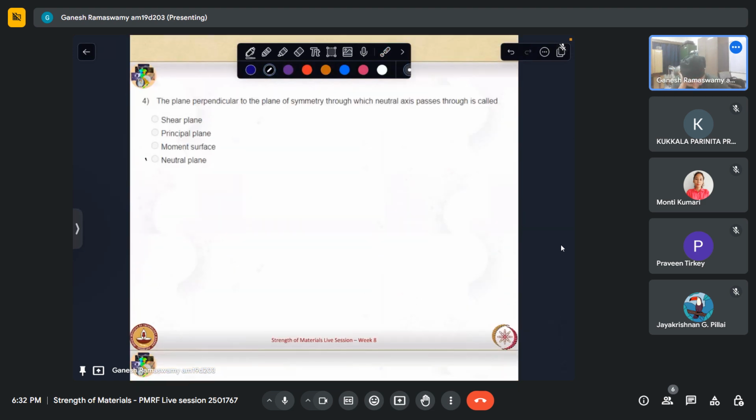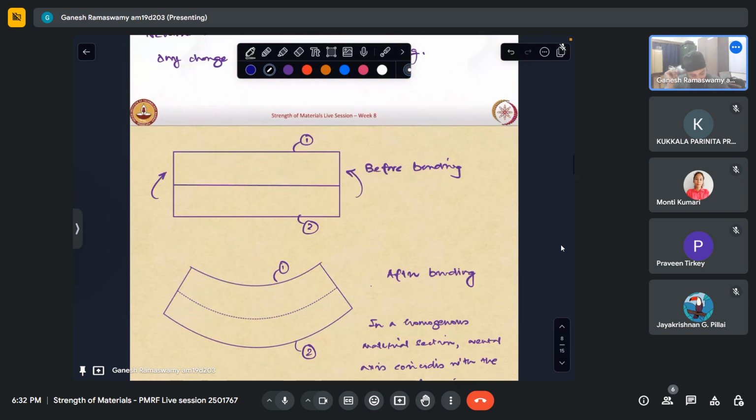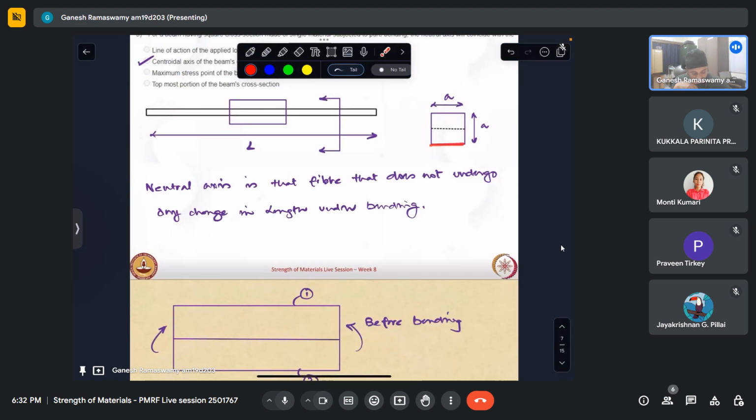But why is this important? It is because we are looking at one surface of that beam. We are not looking at all the surfaces of the beam, because naturally when we see here that there is tension and there is compression, so if there is tension at the bottom and compression at the top, the shape of this square section will no longer be a square because of Poisson's effect. So it will be something like this.